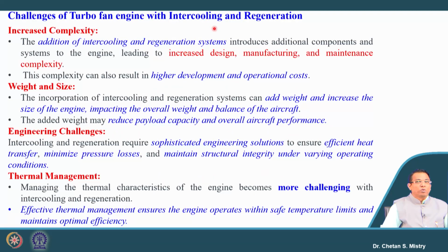So based on the requirement, people are exploring different configurations which are possible for these kinds of engines. Here let's look at the challenges for this turbofan engine with intercooling and regenerator. If we look carefully, by incorporating the intercooling and regenerator, we are increasing the complexity of the design, because it increases the design, manufacturing and maintenance complexity.